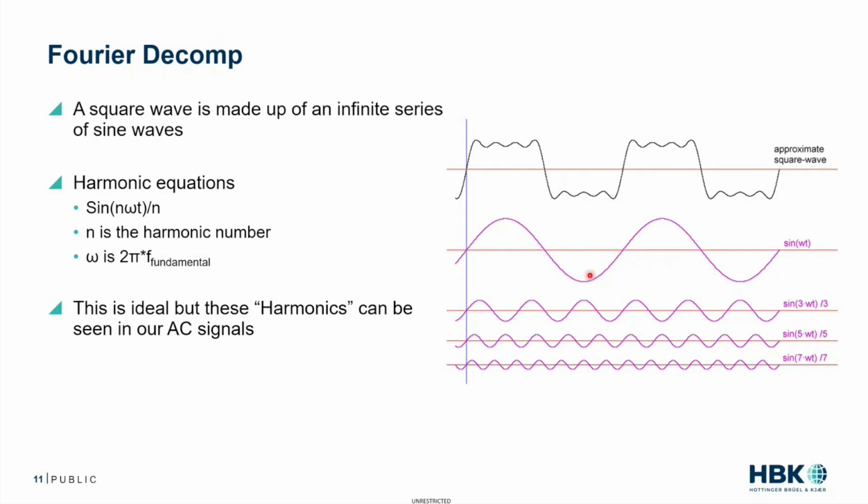But we have a fundamental, which is kind of that carrier frequency, that main frequency, and then other frequencies which are imposed on top of it, which alter the total waveform shape. So a lot of times we will describe these waveforms as the fundamental and then some of the harmonic content. But this is really important to keep in mind, because each one of these harmonics, and granted, this is a perfect scenario again, has a phase between its voltage and current. It has its own element of reactive power, and those are getting added in, and those are getting added in, and those are getting added in.